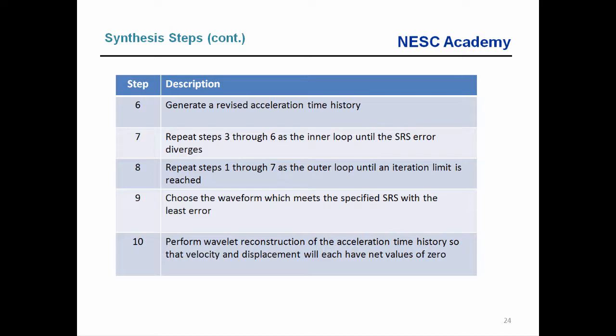Well, for shock, I just decided to be a little bit clever, probably more clever than I should have been, and it's going to turn this into a bit of a Rube Goldberg process. I thought to myself, we could take that damped sinusoid series, and we could model it as a series of wavelets. And if we model it as a series of wavelets, then the net velocities, net displacements, and net acceleration values will all be 0. It'll be a very good stable waveform.